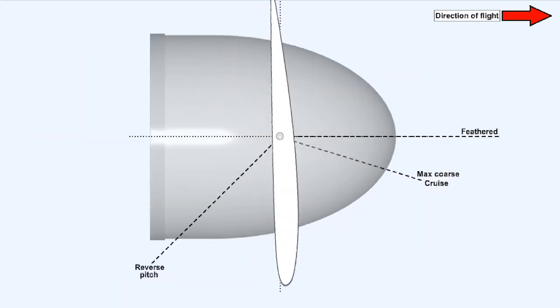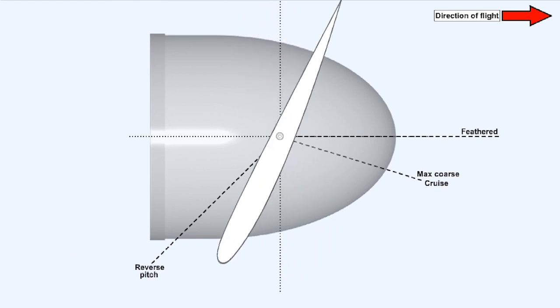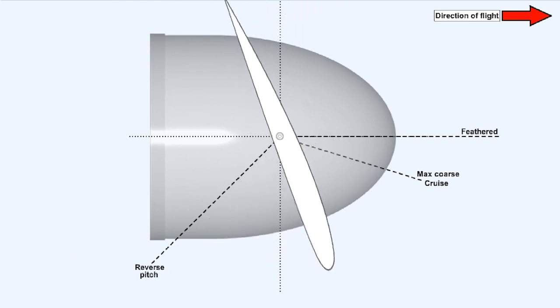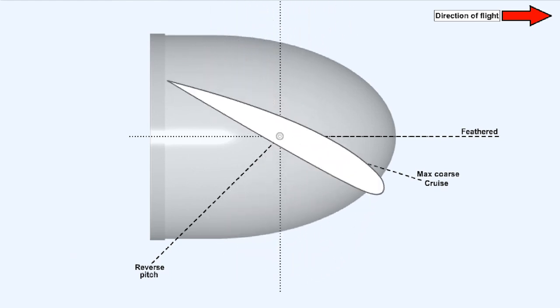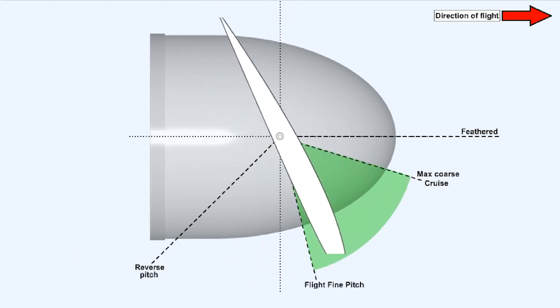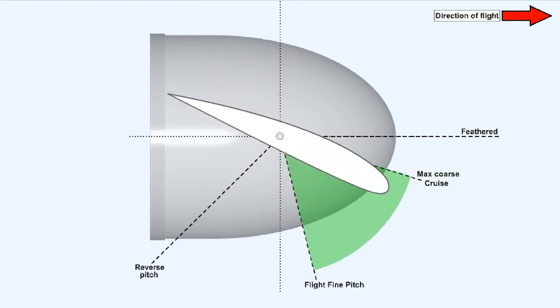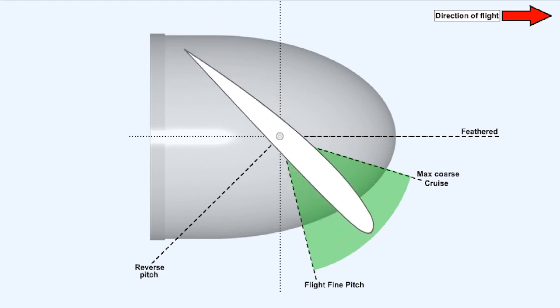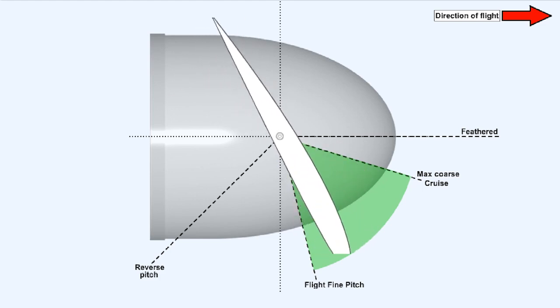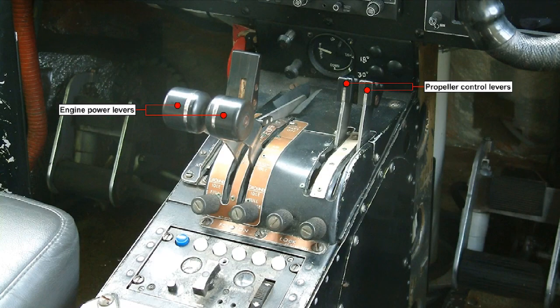Most turboprop engines are provided with a system of propeller control which is defined by alpha and beta ranges. The alpha range is used at high speed, during the takeoff run, in flight and during the initial high-speed part of the landing rollout. The alpha range is selected by moving the engine power lever to a position at or above flight idle.